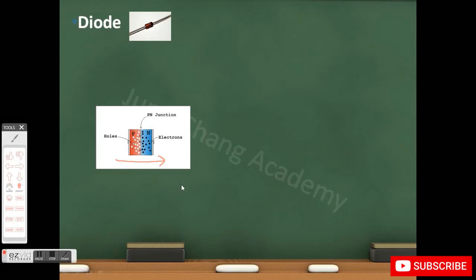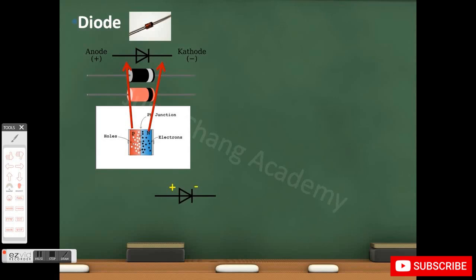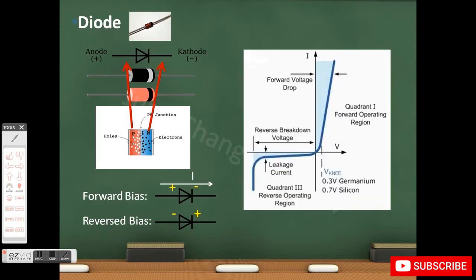Diodes have two terminals, an anode and a cathode. The side where the p-type semiconducting layer is placed is called the anode, and the other side is called the cathode. When the voltage on the anode is higher than the voltage on the cathode, the diode is said to be forward biased, and this is when the diode conducts current. If the voltage on the cathode is higher, the diode is reverse biased, and only a very small leakage current will flow under this mode.